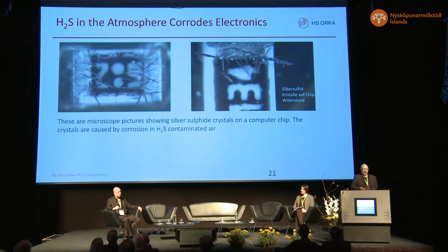Hydrogen sulfide corrodes electronic equipment made of copper and silver and things like that. And what we must do is to have all electrical or electronic equipment in compartments where the air has been cleaned and H2S filtered.